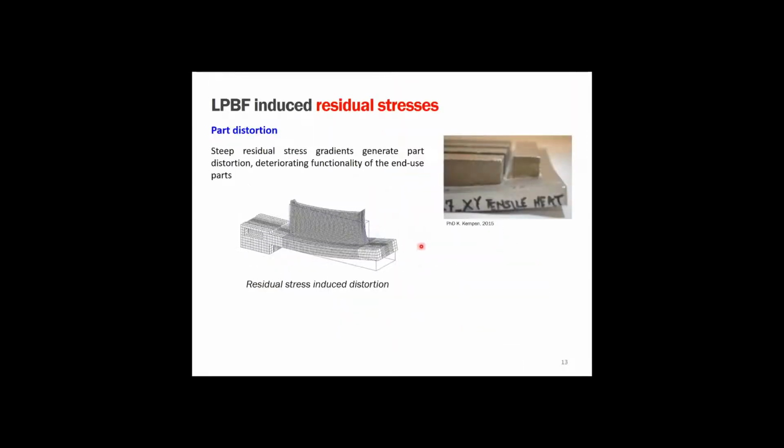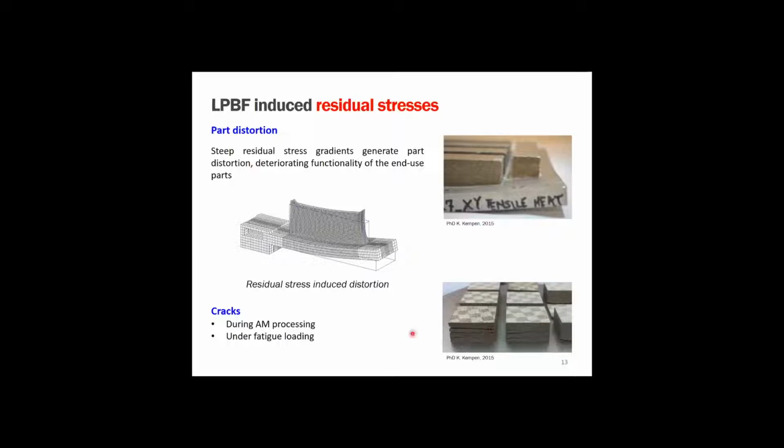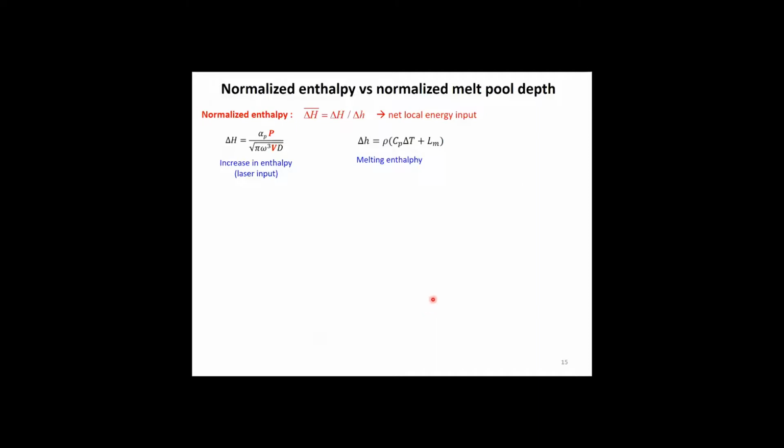Now these residual stresses, they can produce shape distortions, as well known, and you can visualize that typically in parts. This is here a base plate, which is being bent actually because of the presence of these residual stresses. They can cause cracking also during processing, and as discussed by Philippe just before, they have consequences on the fatigue life of the material.